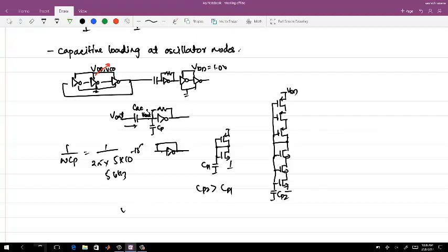No, so this is giga, right? So giga is 10 power 9 and that is 10 power minus 6, right? Into 150. This is in ohm, means still I convert into milli. So then I have only 150 into 10 power minus 3. This is milli, right? What kind of GMs do you work out? It's like millisiemens. Millisiemens means you will burn quite a good amount of current.